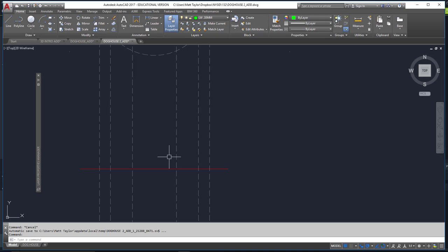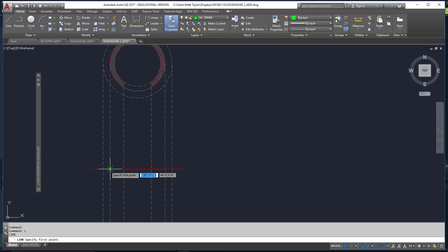The cylinder portion is 2'3", so I can start a line, hold my cursor here. This is the line that's indicating the width of the cylinder right here. I start here, drag up 2'3", that's 27 inches. Wait a second. Start here, 27, there we go. And that's my line here. Actually, I could have drawn that line, I need it anyway, right?